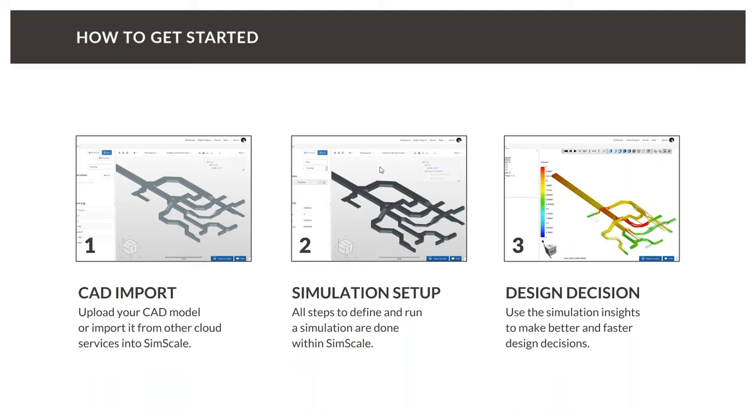And this usually includes two important steps. The first step is what we call meshing. As you can imagine, the computer is using a discrete model of the flow. So we are just calculating the flow, pressure, and velocity for dedicated regions of the model. And these regions, their size and the density of the regions, need to be defined by the user in advance.